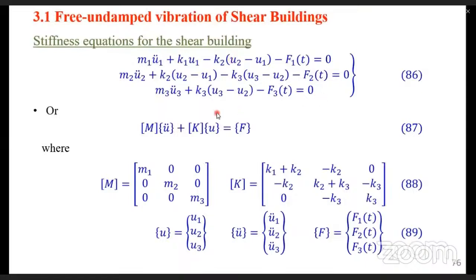So for 2 degrees of freedom, 2 stories, when U3 disappears, the equation is very simple and can be worked out by hand, so that you don't just jump to this level. But of course, if you're not told to derive from first principles, then there's no need to. So you see now there's no M3, and of course no K3 here.